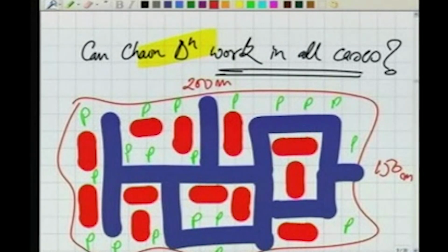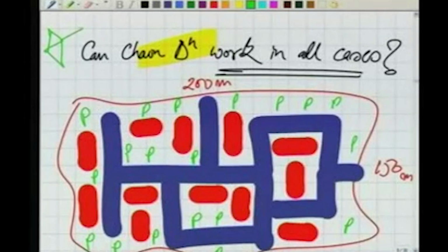Well, what kind of triangulation can we do here? Can we think of some triangulation scheme? The important thing is, in the case of triangulation, all 3 stations should be intervisible. This station, this station, this station, all these 3 should be intervisible. But ensuring intervisibility here is really a problem. For example, let's say I take this as one station, another station. Where should I take the third station? These 2 are visible.